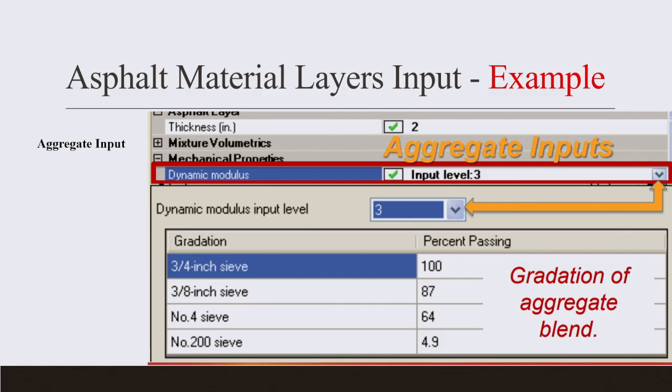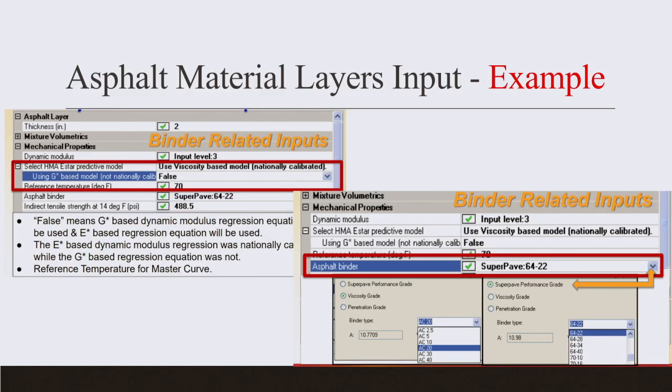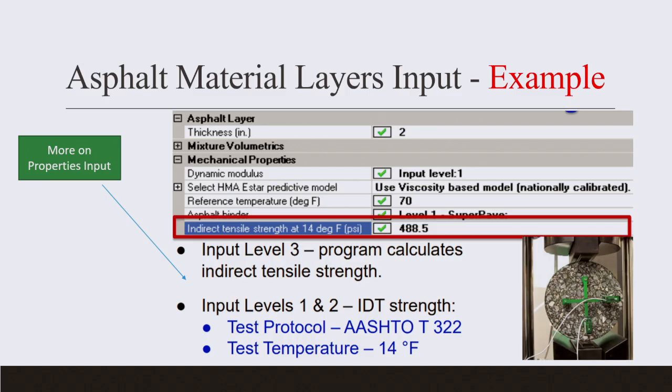And remember, your asphalt is a viscoelastic material, so your climatic effects, the temperature, affect those properties, and those are the things that you input in. In the same way, you also input your aggregates, whether site-specific properties, into the system, and it will use that to do your analysis for you. So the type of aggregate you are using for the various layers will also affect it. I'll be a little quick from here.